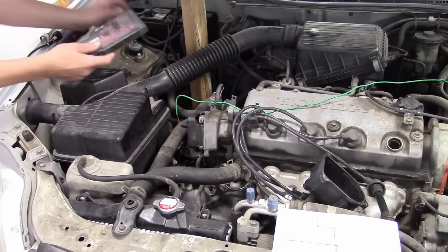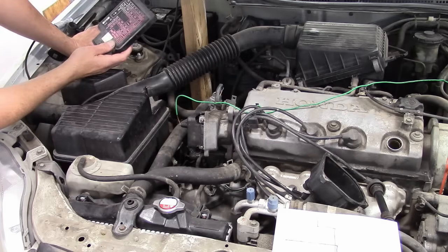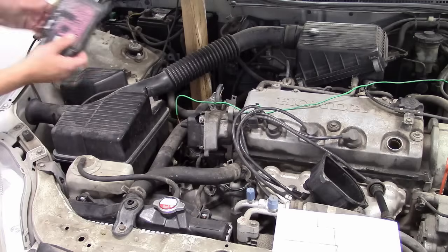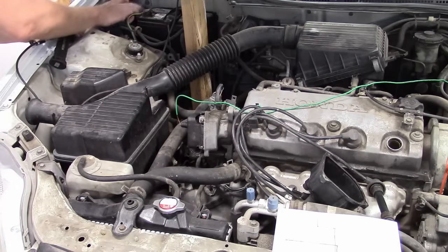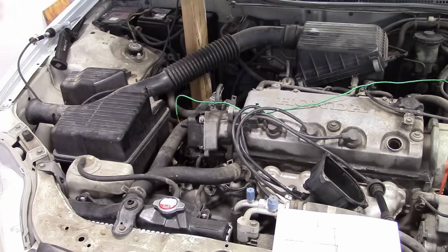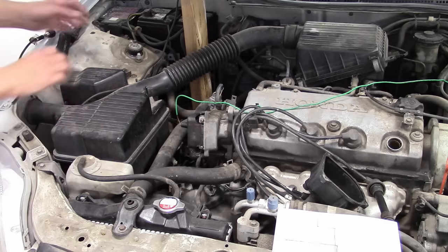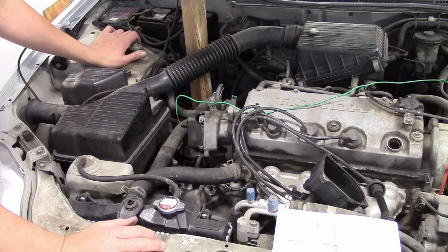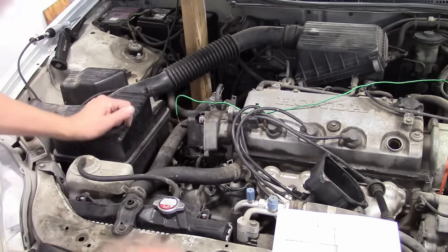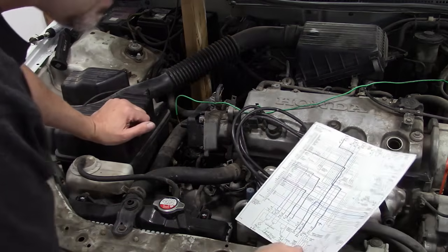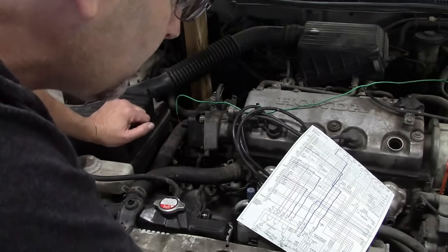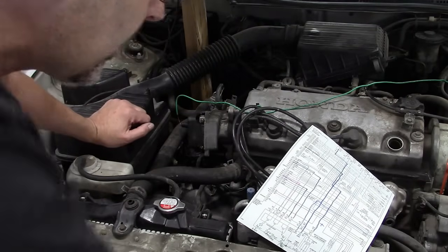Let's see here. Oh, what was I doing here? Oh, yeah. There is no starter relay at this location, so I think I'm going to try to do some tests without having to start the car at this time, because it's a little problematic doing that with the camera and all that. So I am going to look at my wiring diagram, and I'm going to look for that input signal, that ignition input. And I'm pretty sure that was yellow and green.